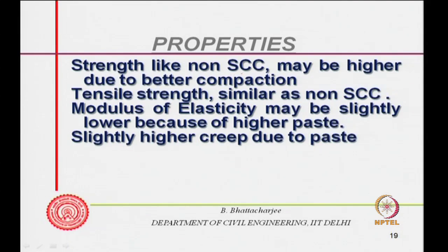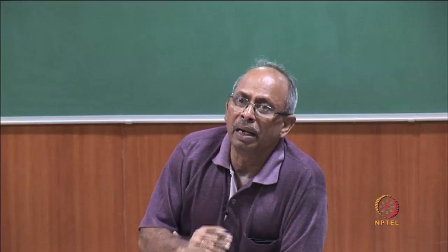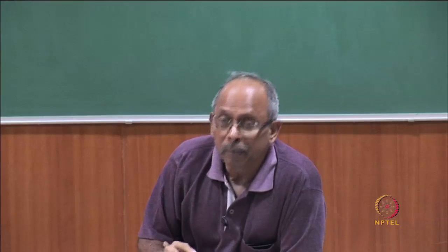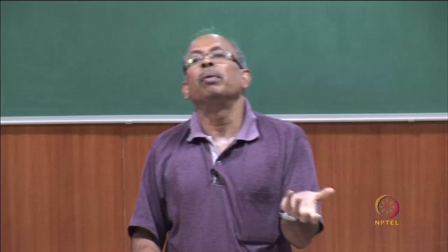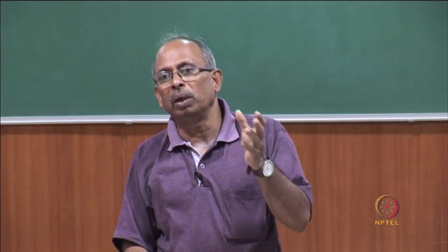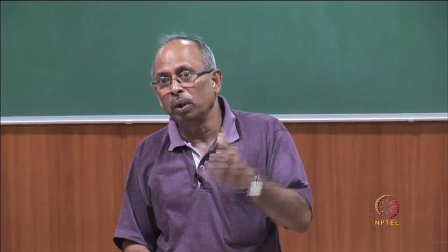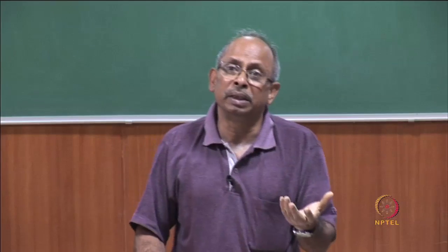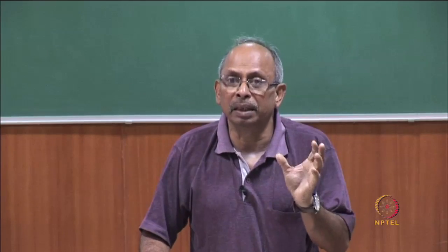Strength, like normal concrete, that is non self compacting concrete, there is no really significant impact on strength, but maybe higher. So, strength is like non self compacting concrete, because finally it is the water to cementitious ratio or water to cement ratio which you are using as a criteria that governs the strength.